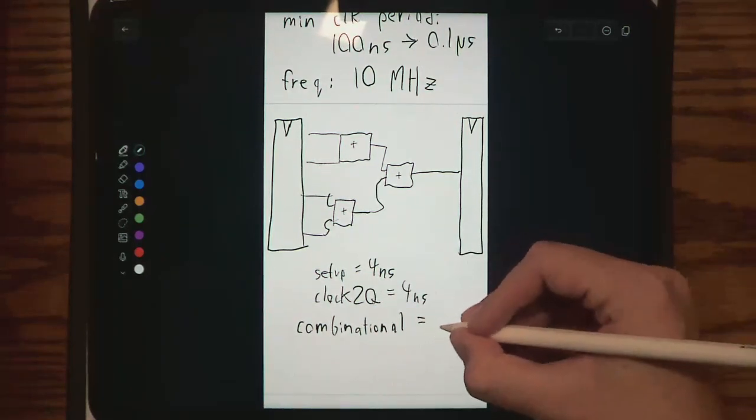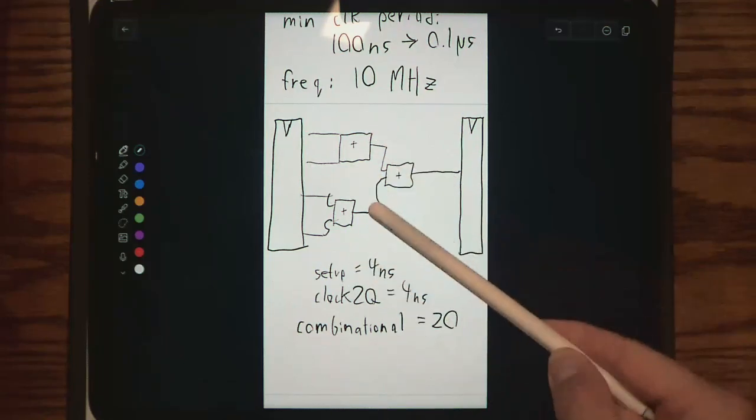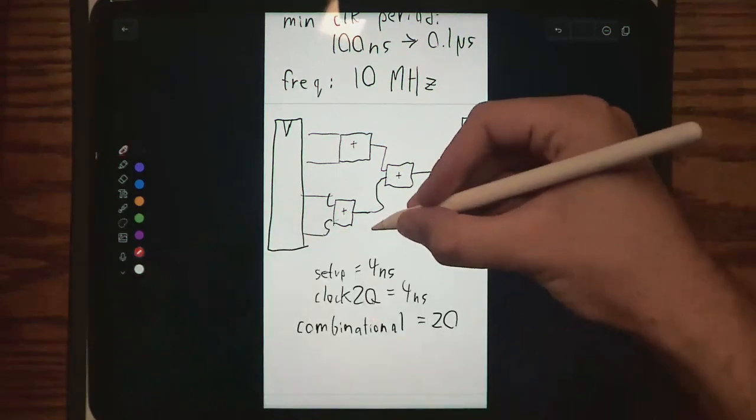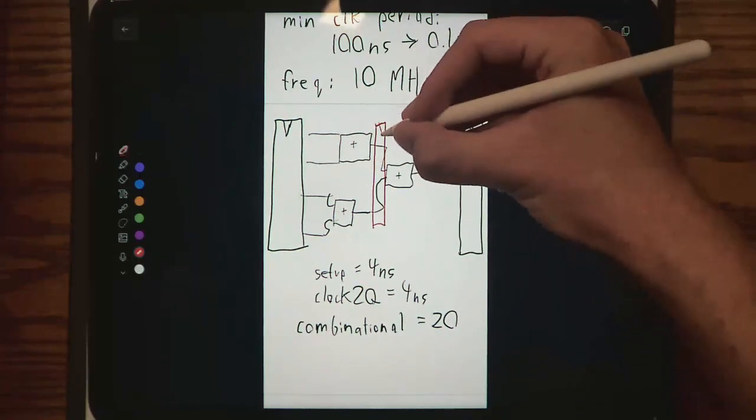But this is not technically fixed, right? We could try to decrease combinational delay. How can we do this? Yeah. You put a mux right in the middle, and then you can work on 2 numbers at the same time. Or not a mux, sorry, a flip-flop. Oh, yeah, okay, I'm totally on board with you. Well, maybe we could just insert a flip-flop right here.